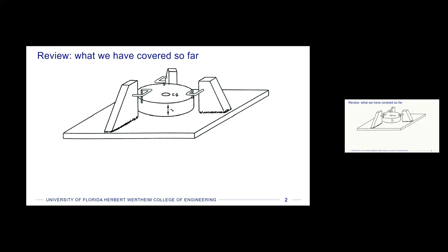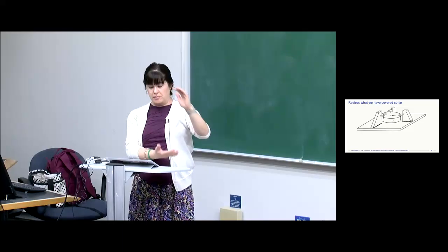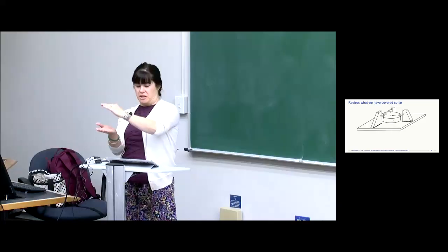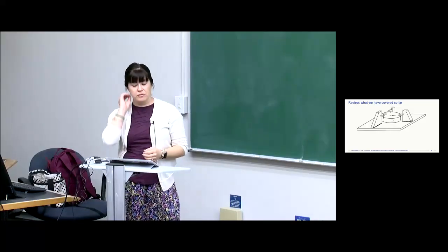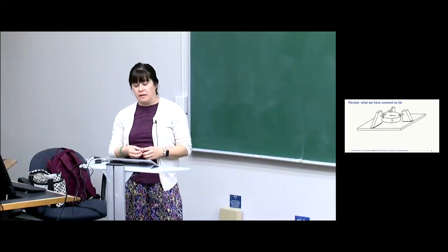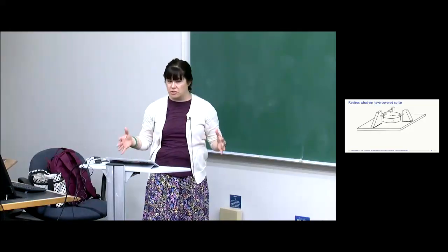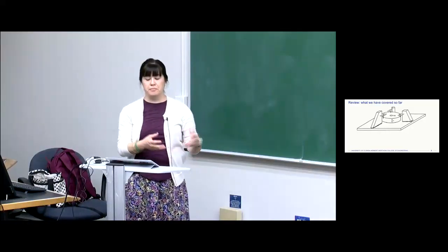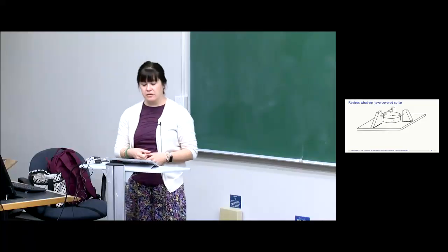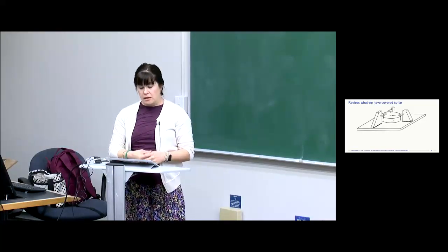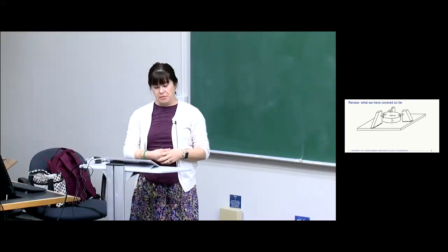And then it also told us that there was a loading spectrum, right? That it was full scale for some portion of the journey, and then it was 3/4 of that for some portion, and then half of that amplitude for some portion of the journey, right? And so if the stresses were high enough to use a cumulative damage theory, then you could have pulled that out of your toolbox and used that as well. So that's what we covered before we got to this problem.